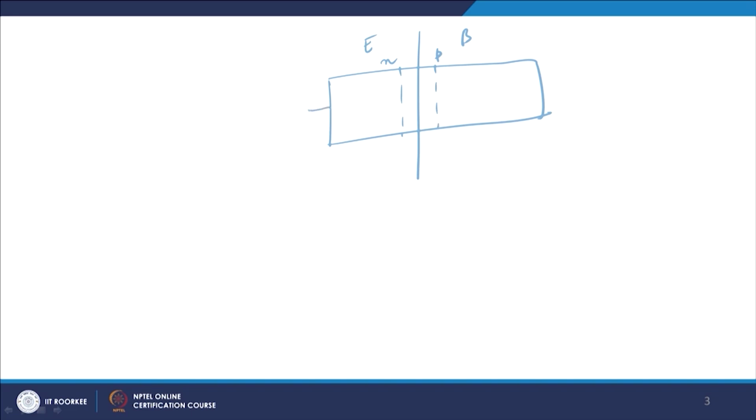Now, what I do is I first forward bias it. So, I do like this. As I do it, current flows and there is no problem. Then I have to reverse bias it, so I just remove this part and I add something like this. Once I reverse bias it, the current stops, because the depletion thickness becomes quite large and there is no current. Then we again go from reverse to forward.